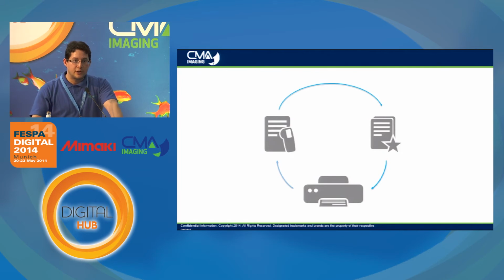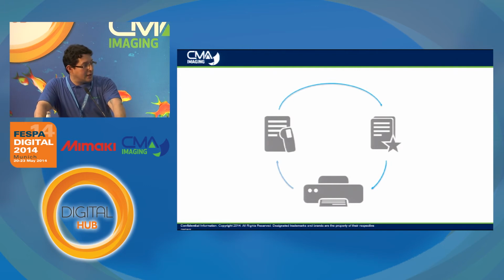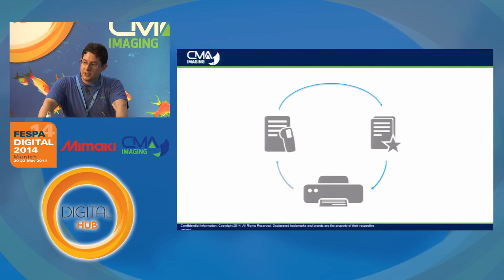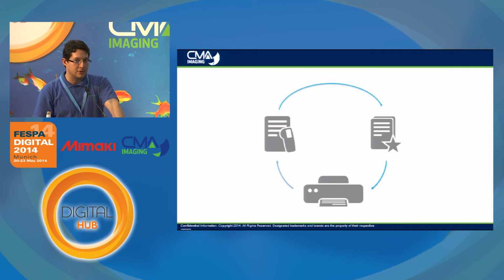We use in our software a patented four-dimensional color management technology because what we aim to do with this technology is to standardize the colors and to use some standard profiles like the ISO Coated V2 or others, and we put that together into what we call device links. So it's combining a target profile and the printing conditions. We put that into one same profile, and then we can get the same colors on different printing methods.